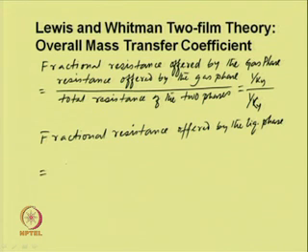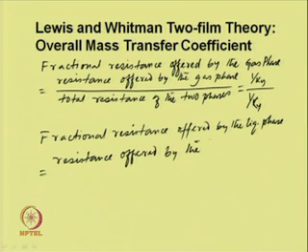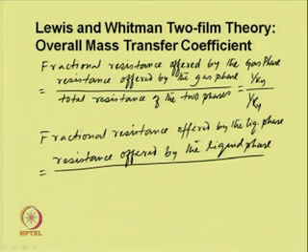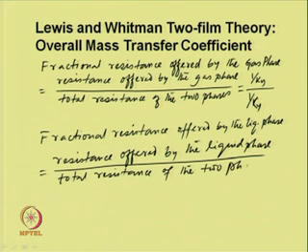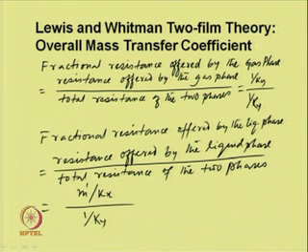It will be equal to the resistance offered by the liquid phase divided by the total resistance of the two phases, which is equal to m dash by small k x divided by 1 by capital K y.